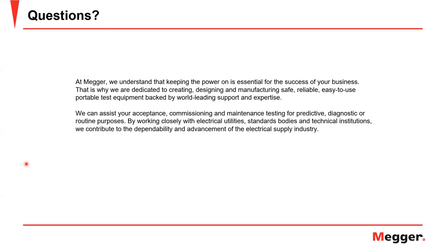Our first one I'm going to send over to Mohit. Is it better to make the CB trip before the fuse due to the time spent replacing the fuse? Okay. It could be. It all depends on the utility practices, as Mike was explaining in his presentation. Various utilities adopt the philosophy of a fuse saving scheme, whereas some adopt a fuse blowing scheme. In the fuse blowing scheme, all the fuses are gone, and then you have to send manpower out in the field to replace them.